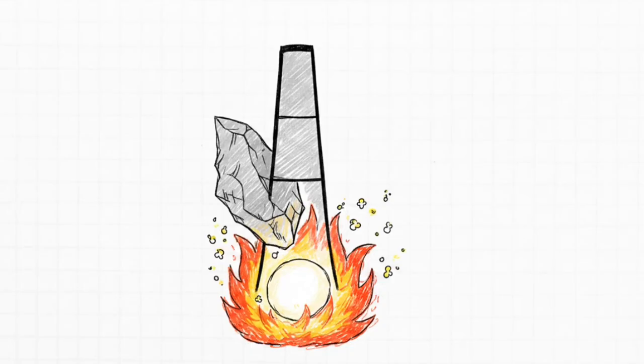Let's look closer and see how this builds, literally. After the preheater, the material passes into the precalciner. Here we get some real-time heavy-duty chemistry happening. Most of the limestone, which is chemically known as calcium carbonate, undergoes a profound chemical conversion. Under these extreme conditions, it transforms into calcium oxide. The rock is fundamentally changing at a molecular level right before our eyes.